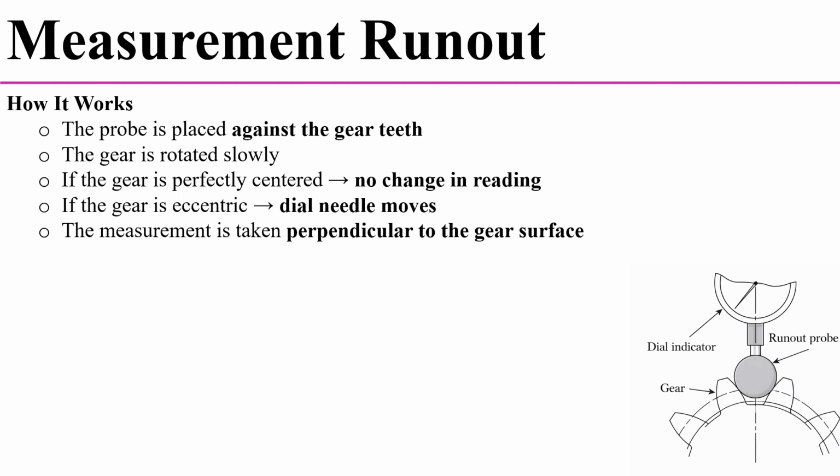So next we have to see the working procedure. First we have to place the probe against the gear teeth, and we have to rotate the gear slowly.